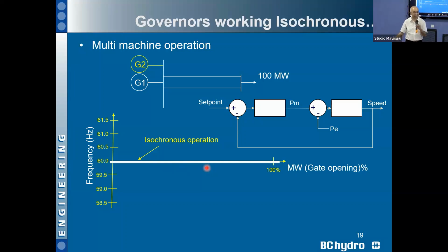and the other might be 50 or 49.999. So if you have two set points inside the governors, those two governors will try to fight each other. One is trying to make the frequency 49.999, and the other will try to maintain the frequency at 50.0001. What will happen is, the unit that has more power will take precedence. The other one has to follow. Those two will be fighting each other all the time, and there will be a frequency variation all the time with a fixed oscillation frequency. The oscillation frequency depends on the inertia of both units and the power of both units.